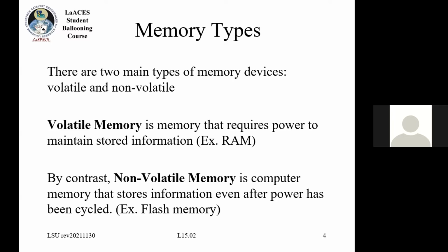The real-time clock that you're going to use, that information is stored in volatile memory, but if you give it a little bit of power, it can keep it on. But in general, if there's information we are recovering later, we want to put it in non-volatile memory.